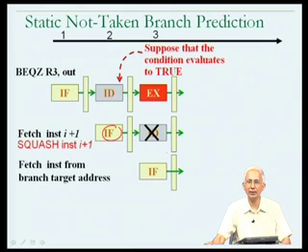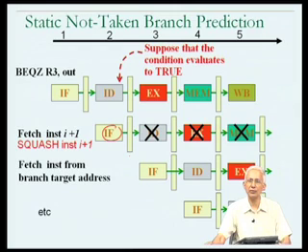Its activity should be cancelled, which I indicate by an X mark, suggesting that the instruction whose activity is happening in the ID stage at that point in time should be ignored, and any effects that it tries to produce should be negated by the hardware. Similarly, the instructions proceed through the pipeline as cancelled. So, we have this additional notation of an annulled or cancelled instruction going through the pipeline.